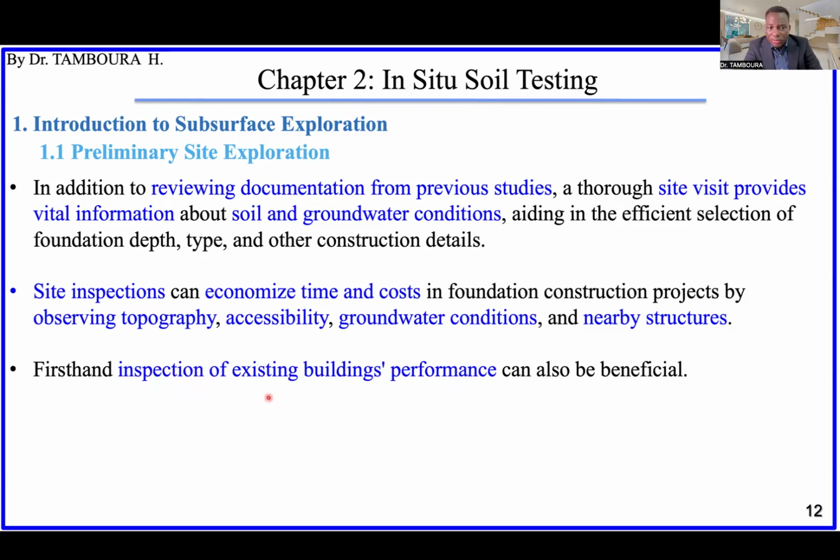And also the inspection of existing buildings' performance can be beneficial. That is very simple and very important. For example, if you want to build a house or a building at a place, and you go there and notice that the buildings near this location are all experiencing excessive settlement, then you may think that maybe I need to be careful so that my building will not experience excessive settlement.